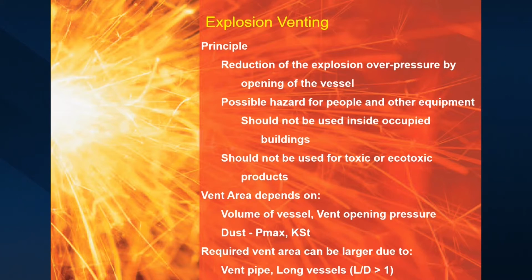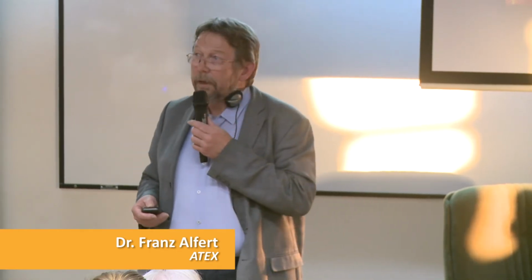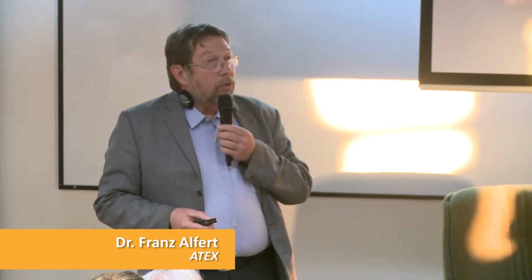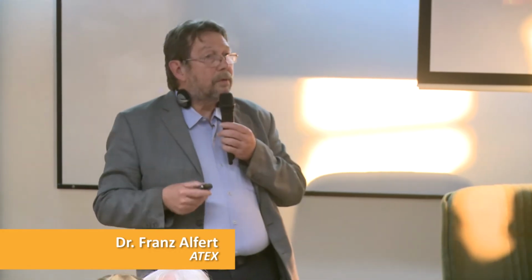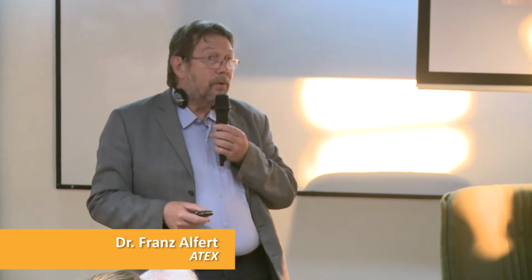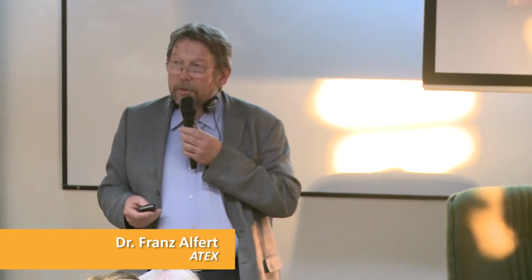What we must not forget when we do a vent area design is that we have to vent to the outside, and that should be a very important rule: we do not vent into buildings, into rooms, because that would create a pressure wave in the room. It would create a dust cloud if we have dust on the beams and everywhere. And as I said before, it's only very little dust that we need. And then we would get a secondary explosion, which is turbulent, which can be devastating.